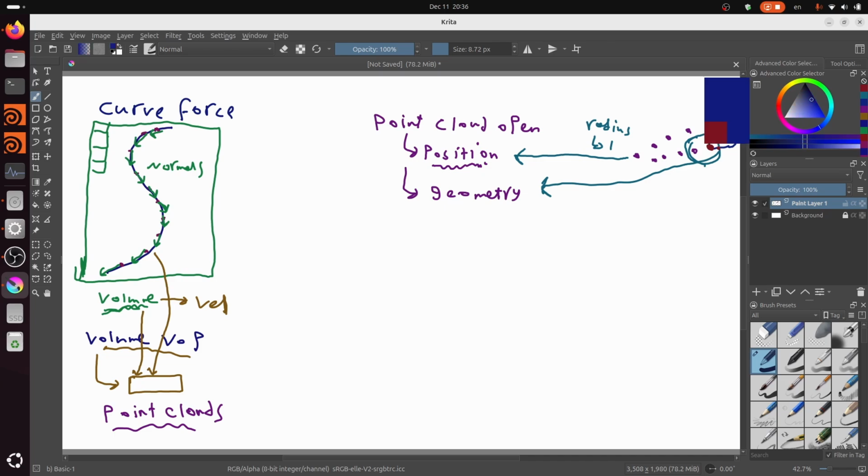Okay, now after you found these points, you can grab things from them, or you can manipulate them in a lot of ways. So there are a lot of point cloud nodes, but we are going to use a node called PC filter. And this node just grabs specific attributes from the found points.